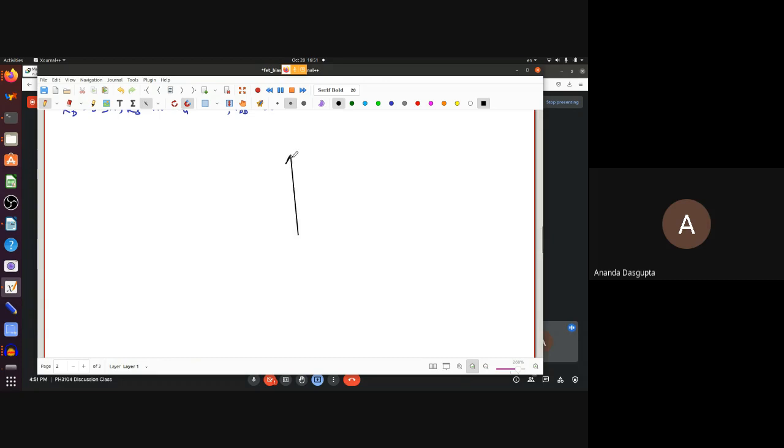Look, this is your ID versus VGS graph, where the curve is like this. Of course, the quadratic equation that I've written down would have given you a parabola, but you really have half of a parabola. And so this is the Shockley relation, this red curve, and VGS is minus IDRS.